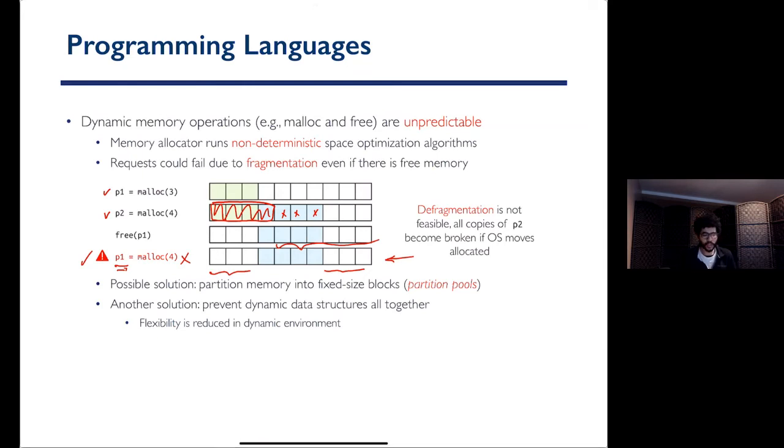The other solution is to just get rid of dynamic allocation altogether. So this is actually very common in real-time systems. They don't allow dynamic allocation. You don't have malloc, you don't have alloc or free or new. So anything that you want, you have to statically allocate at the beginning, right? So either your code compiles and loads, or it doesn't. So you don't do it in real time when you start running. At runtime, you don't need to allocate memory.